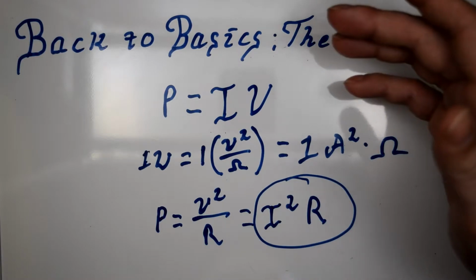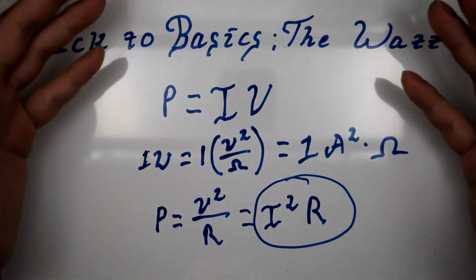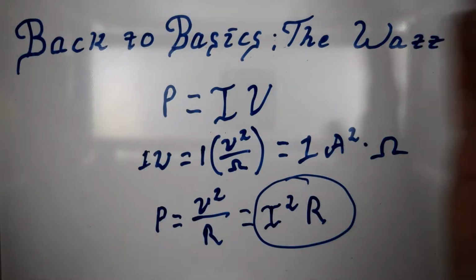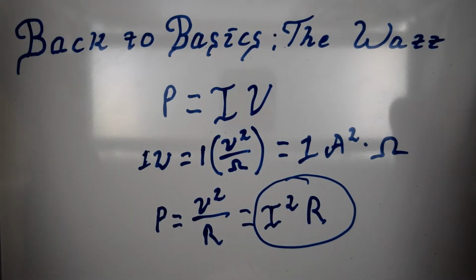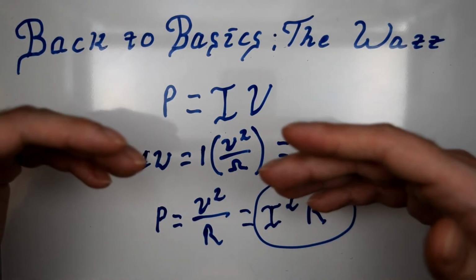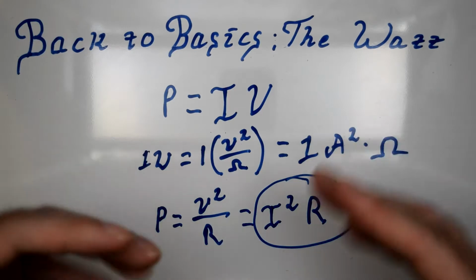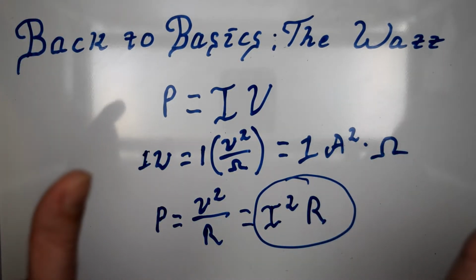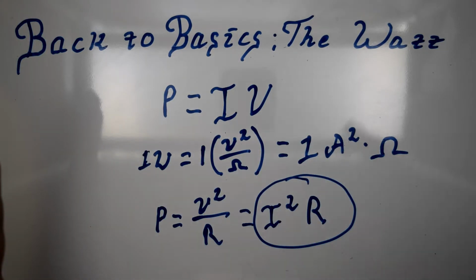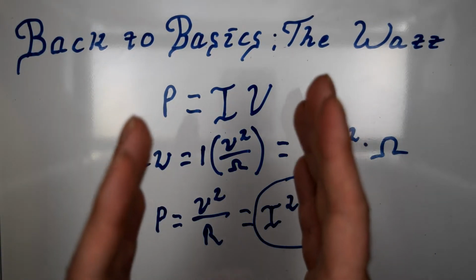In general, we only talk about I squared R losses in the electrical field when we're talking about how large current over a long run of a conductor generates heat, and you lose power to that heat, which is why voltage at the outlets is typically, at least here in Canada, 120 volts, but it can be anywhere from about 114 to 122-ish, but typically it sits around 117.